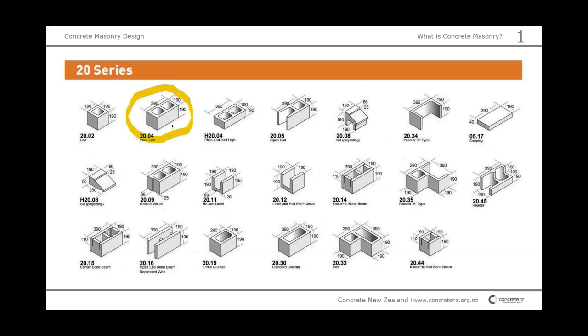However, the concrete masonry block manufacturers make it extremely easy for you. They also provide off the shelf half length, half height blocks, corner blocks, and even sill blocks with a rebate and a sill already in place, capping stones, and blocks to place your horizontal rebar for lintels and beams, etc. So it's a rich variety of items off the shelf, making your life extremely easy.